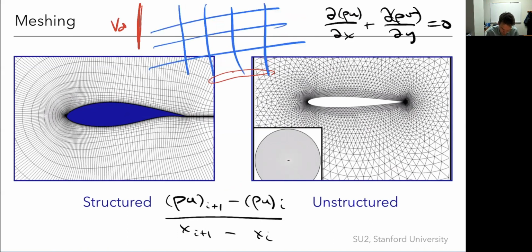And instead of thinking about putting things in the cells or on the nodes, I could think about the cells. So I could say, well, here's a cell, and I could think about it like a control volume. There's some velocity coming in, some going out. We've done this a bunch of times where we did a little integral momentum approach. So the first one is like a differential approach. This is more like an integral approach. We call this finite volume.